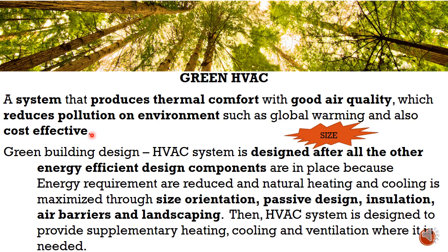Alright, so green building design. All design of HVAC system will be done after all the components are designed in such a way that it is energy efficient. After all the energy efficient components are in place, only then we design the HVAC system. Why? Because the energy requirements are reduced, and natural heating and cooling is maximized through site orientation, passive design, insulation, air barriers, and landscaping.